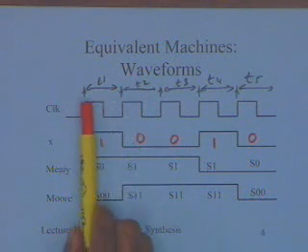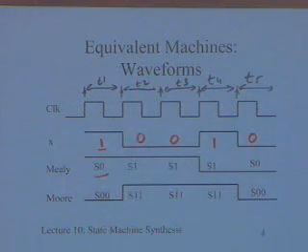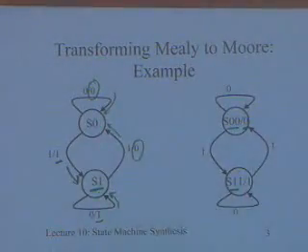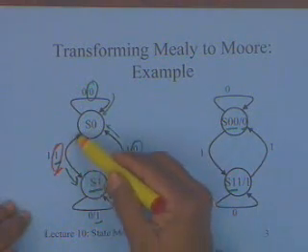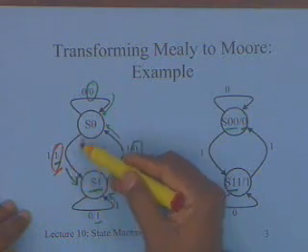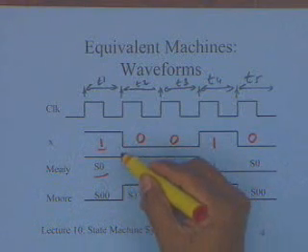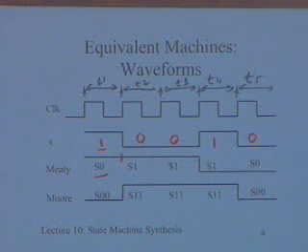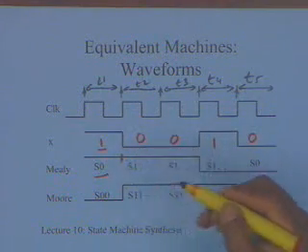But with the state S0 and my input is 1, my output will actually be 1, because this is what this Mealy machine defined. If S0 and input is 1, my output is going to be 1, and because I am on this particular transition arc, I am going to have an output of 1. The actual transition to state S1 will only occur in the next clock period, because the next state will become the present state, and at the edge this particular activity takes place, and so I have S1 over here.